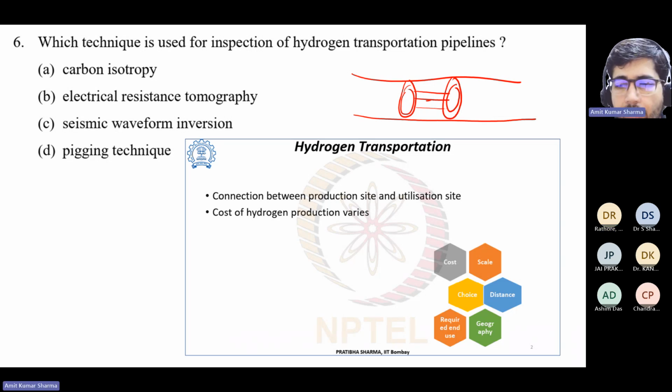Is it underground or elevated? Underground, because when we are talking about the pipeline, it will be below the ground. Normally it will be around 2 or 3 meters deep, depending on the level you need, based on the pressure drop. It will vary. Generally the minimum is 1 meter below, and you can go up to 2 meters, depending on your pressure drop and other things.